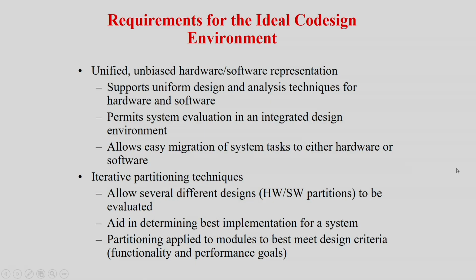But here the hierarchy is C language, on top of it is a hardware, but it's not exactly hardware, it is a hardware written in Verilog and VHDL, and in entirety there should be a simulator which can take the hardware in VHDL and the C language which is running on that VHDL version of the hardware and tell how the total behaves. Very, very difficult to get something like that.